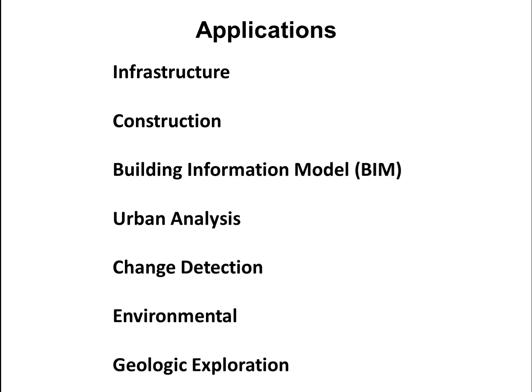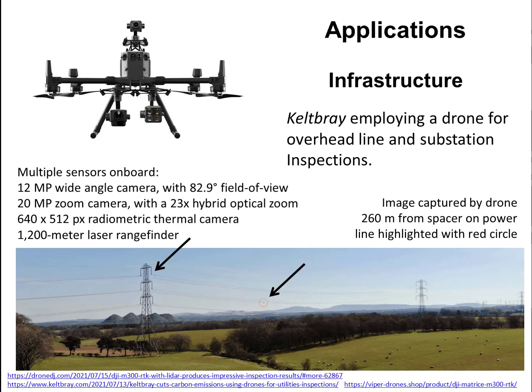So finally, we'll look at applications. Mostly it's on the engineering side, and at the end we look at environmental and geologic exploration. So this is a very interesting company, Keltbray. They're employing a drone for overhead line and substation inspections. Example of the drone they're using with multiple sensors, and they put on this one drone a wide angle camera, a zoom camera, a thermal camera, and a laser rangefinder.